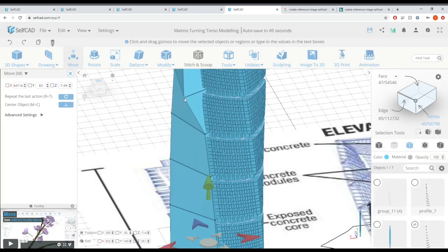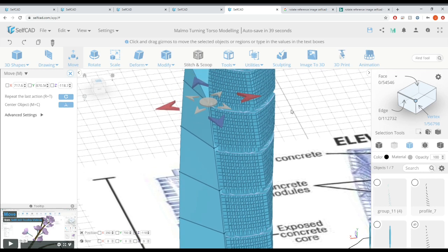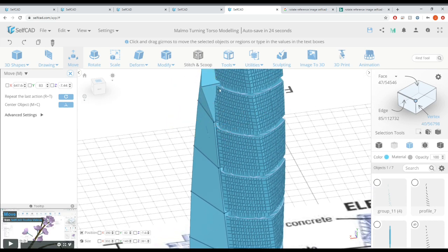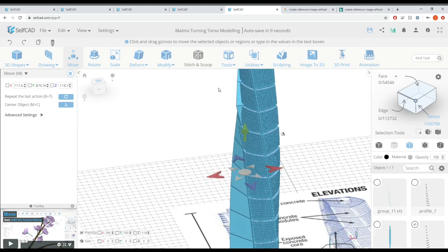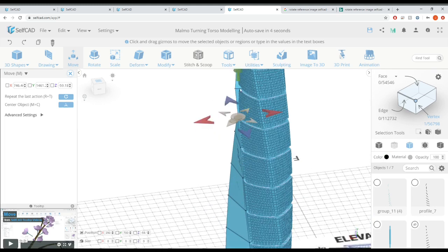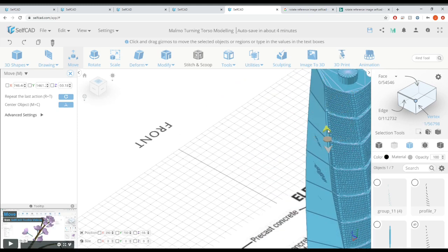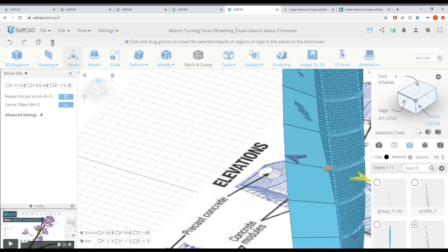As you can see, now I'm moving the vertex a lot more accurately. And remember, when you want to select the next one, make sure you click outside of your selection, outside of your object, to deselect your vertex. Otherwise, you'll be moving quite a few points that you probably don't want to at the same time. So a few more adjustments to the vertices on top, and we should have it. There you go. So when you rotate it to a different view, you would realize that actually there are a few more adjustments to be made.